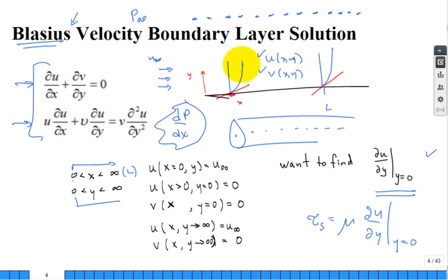in the y direction. Somebody says, well, what about close to the plate? Does the pressure there change as you move along? Nope, does not. So basically the pressure is not a function of x nor a function of y. I skipped that step and I'm just saying it in words, but it comes from the y momentum equation. All right, so we don't have a pressure gradient pushing it. What does this term in the momentum equation represent?